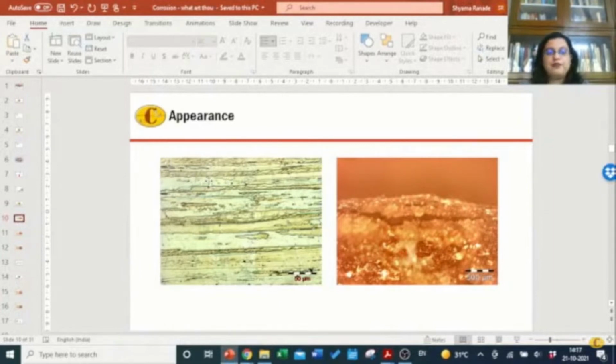So, you have longitudinal grains of aluminum, and on those longitudinal grains, on the grain boundaries, there will be intergranular corrosion, which will lead to lifting off of the grains. So, basically these grains, these entire layers, are going to be lifted off the surface. So, if you have a wing, you can imagine lifting off of the layers is disintegrating of the wing structure. So, that is very dangerous.